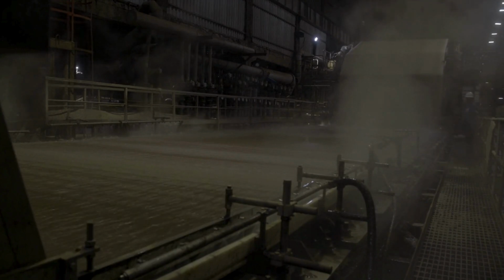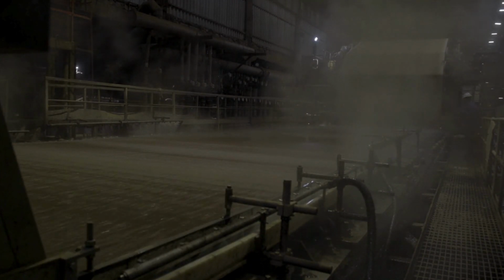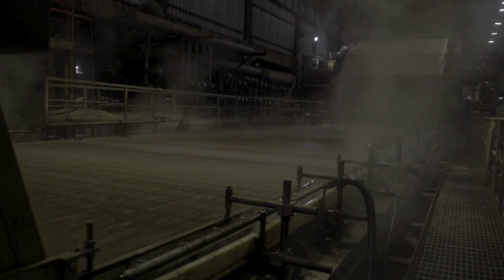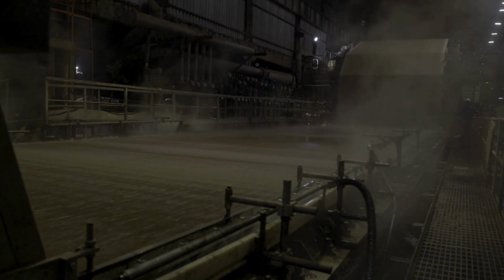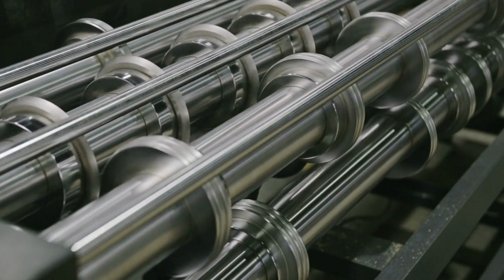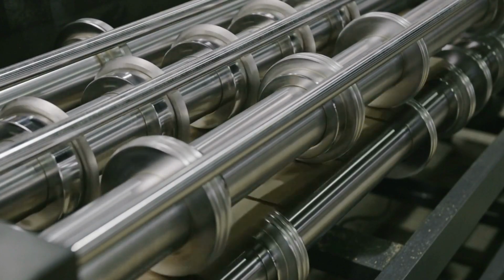The refined pulp is diluted with water to create a slurry. This slurry is 99% water and 1% fiber, ensuring smooth sheet formation. Additives, such as fillers, clay or calcium carbonate, and binders, are mixed into the pulp to enhance properties like brightness, smoothness, and strength. Then we have the sheet formation on the paper machine.